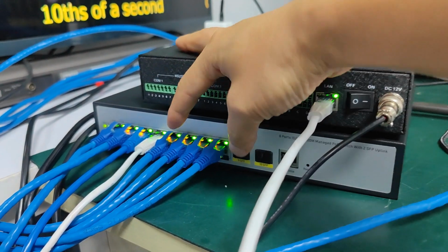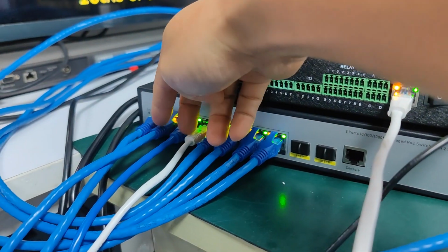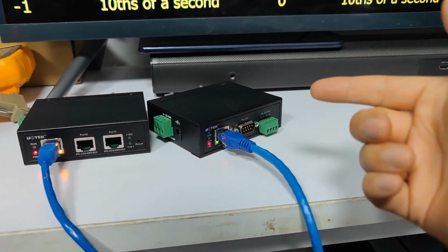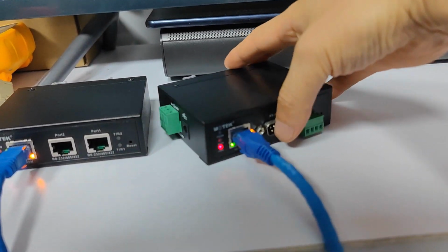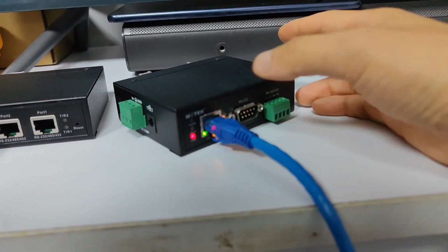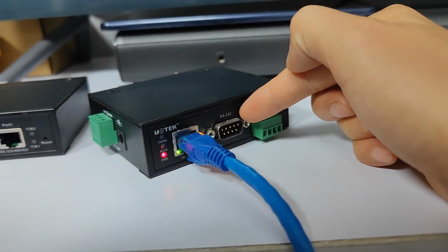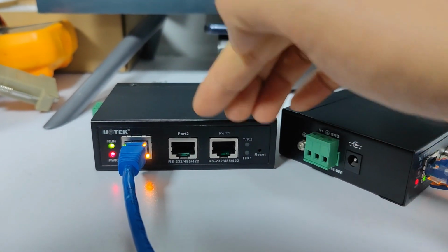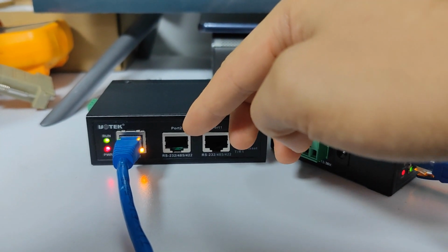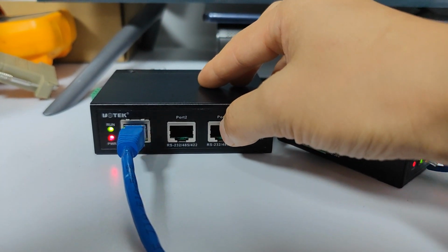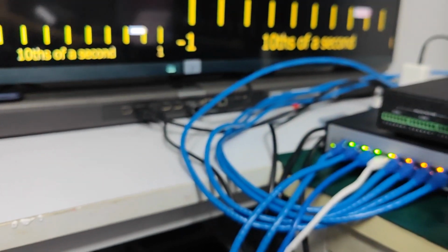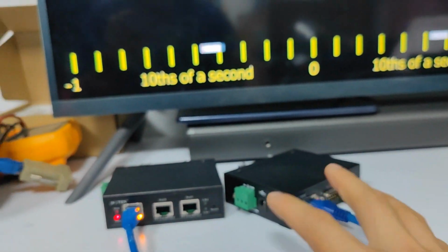From the PoE switch, we can check out that we have two LAN cables connected to the RS232 server here, the IP to RS232 server. We have two types. The first one is where we're using TCP/IP to the DB9 RS232 port, one port only. The other is where we're using TCP/IP to the RJ45 port as the RS232, 485 or 422. Later I'm going to send the TCP/IP from the control host to these two servers, and then we can control the displays on and off by the RS232 commands.